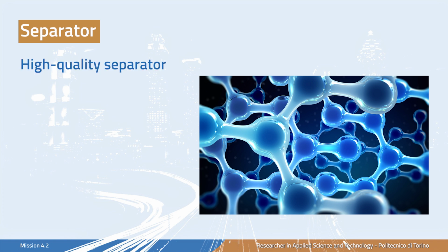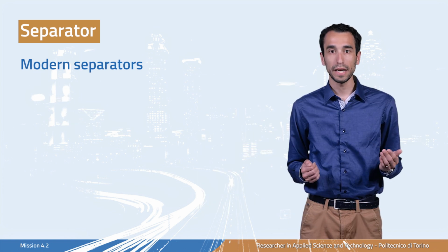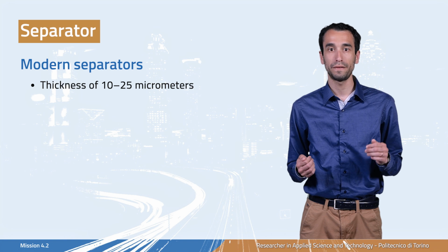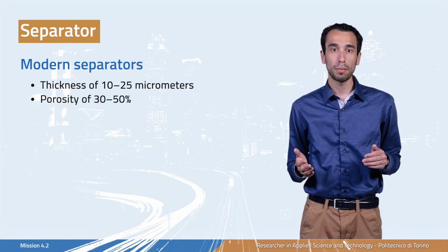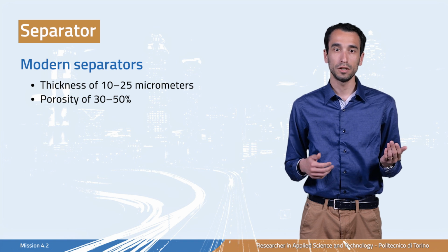A high-quality separator must have excellent mechanical strength, enough porosity to allow the passage of the liquid electrolyte, thermal resistance, and electrochemical stability in the adopted voltage window.